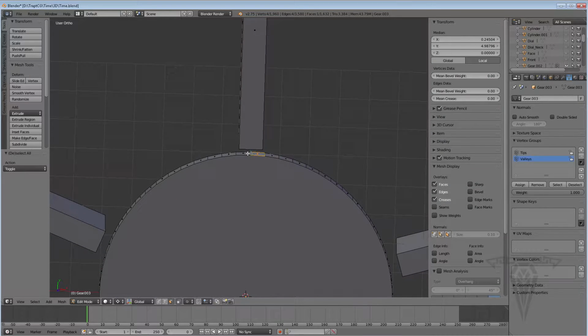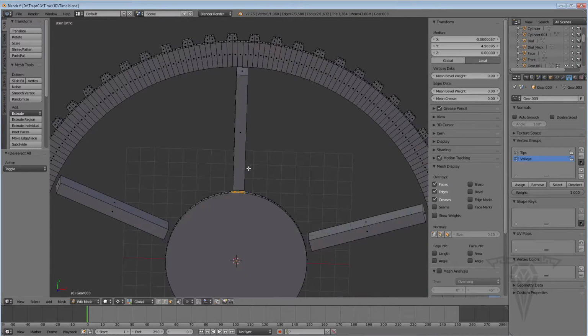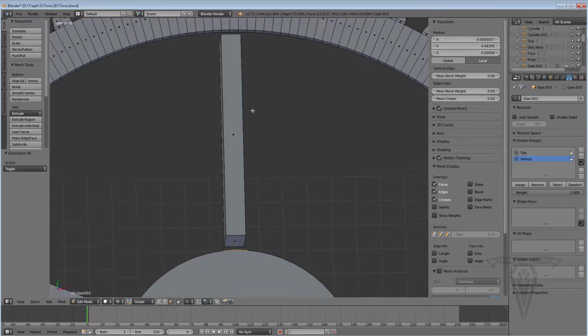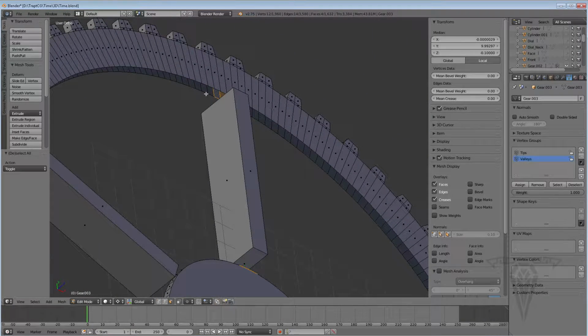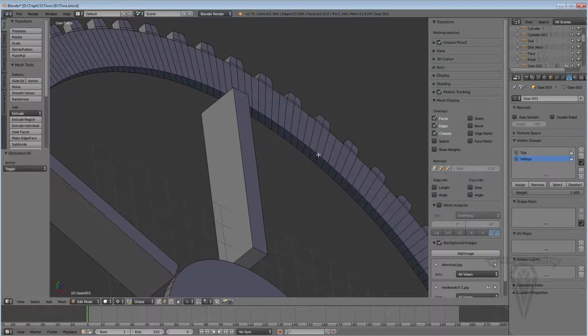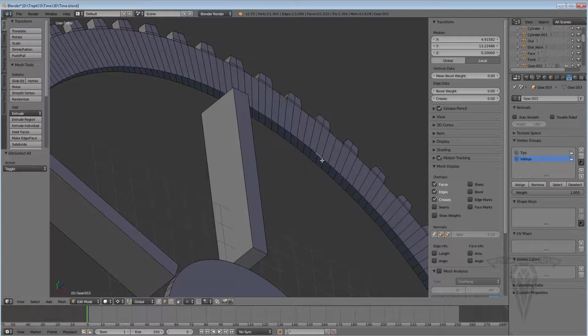I'm going to grab these 2 polygons by holding down Shift and selecting them. Come back out to the top and hold down Shift and select these 2. Oh yeah, we need to create the bridge here because this is an empty hollow. So I'm going to go to Edge Mode. I'm going to hit A to deselect all. I'm going to click on this edge, Alt click. Oh, nope, it's Control and Alt.